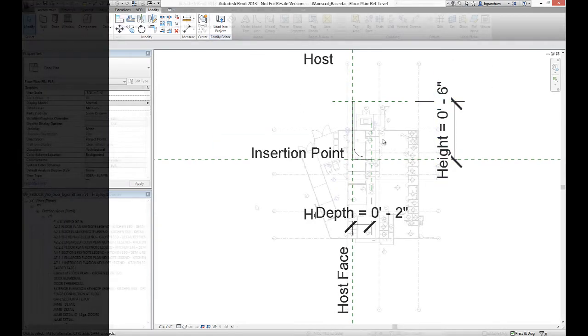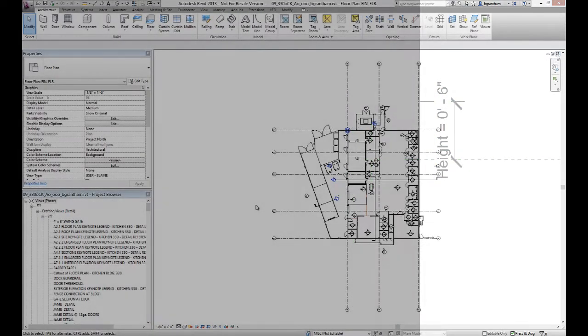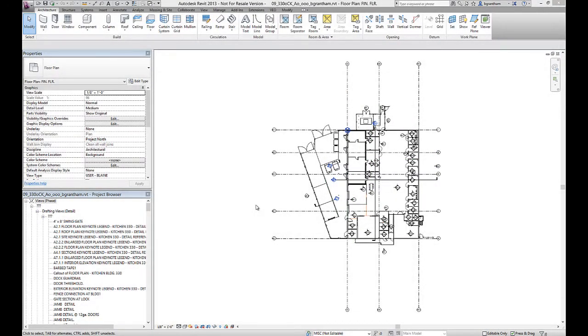We can go ahead and close this and then open up our project. So once you have your file open, we need to apply the profile that we just created to a wall type that we're about to create. Now this wall type consists of basically two parts. You have a structural component, which is within the core, which is going to be the 1/8-inch thick wall covering. And then we're also going to apply a sweep. That sweep will consist of the profile that we just created.